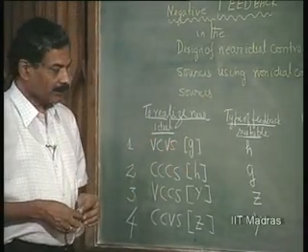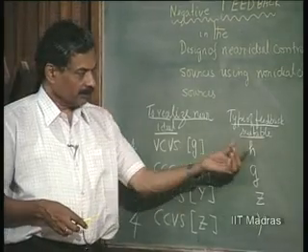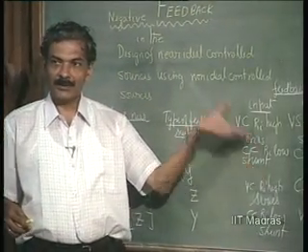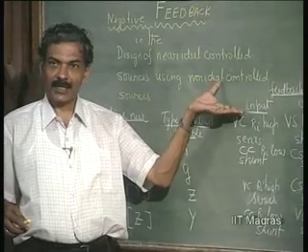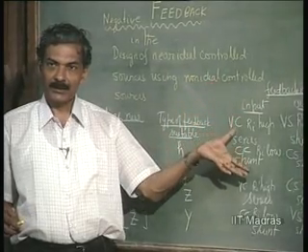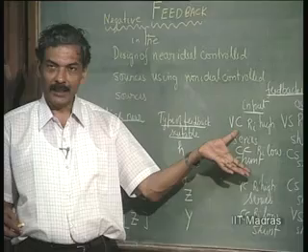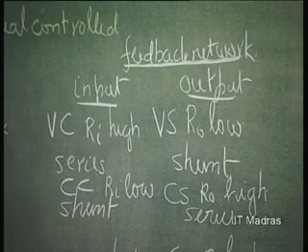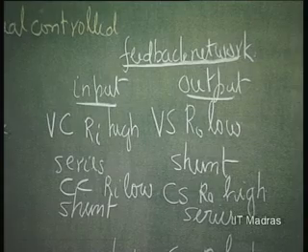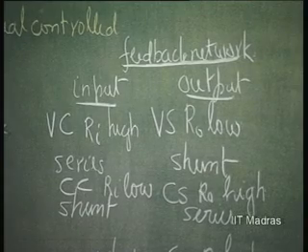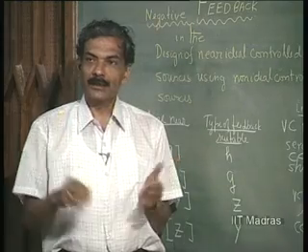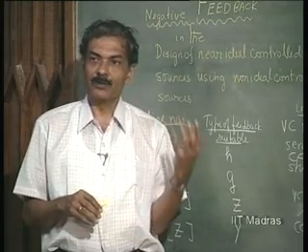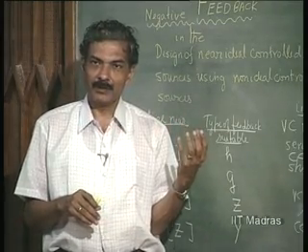Mathematically also we concluded that H parameters add in this feedback arrangement. The H parameter of the amplifier gets added to the H parameter of the feedback network, and then when you convert the H matrix into the G matrix, which is the inversion of the H matrix, you will see delta H coming and influencing every parameter. It is like loop gain; delta H is similar to loop gain.